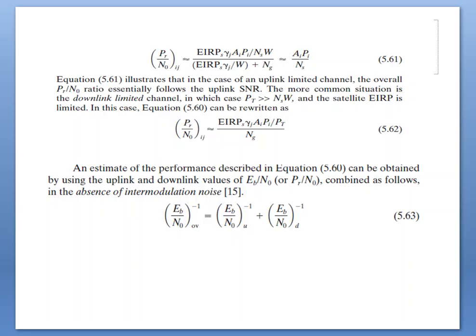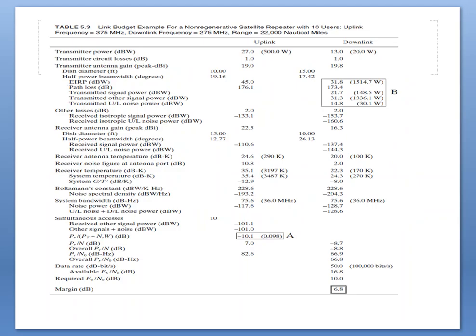The power of the transponder is shared primarily among the various uplink transmission signals. Very little uplink transmission is transmitted on the downlink. The performance of the repeater is constrained only by its downlink parameters. Here, the link analysis example for the non-regenerative repeater is explained in the below table.